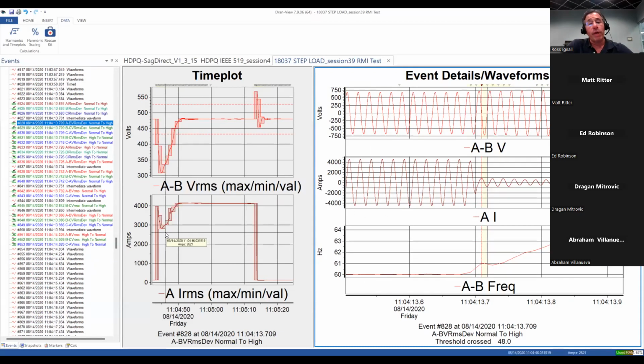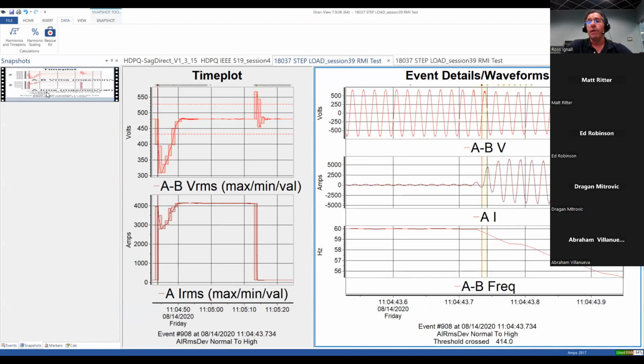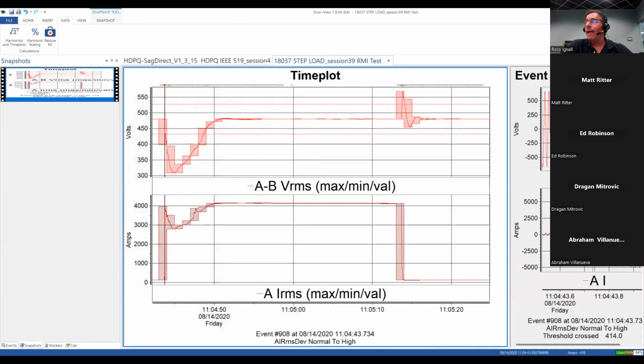But again, the motor inrush application, or the inrush or the cold load pickup, is very similar. You're really looking for just that firing over here, like I showed you in the snapshots. That energization going from 0 to whatever it's going to max out and peak when it turns on. So it's very similar, but a little more specific and honed down application.